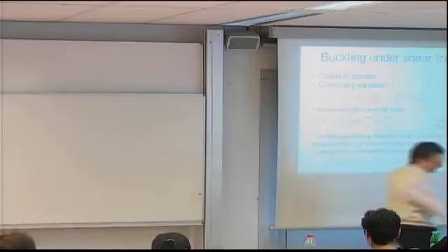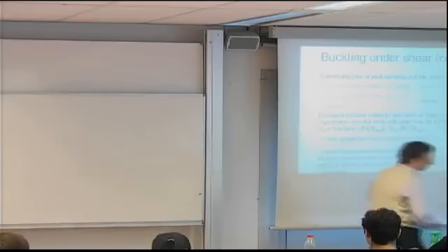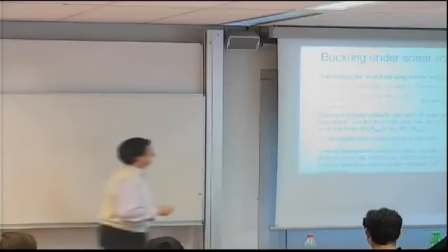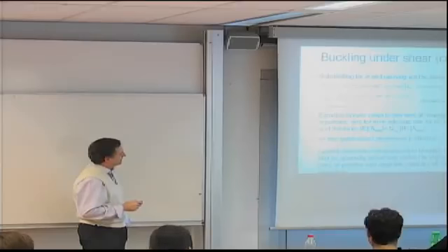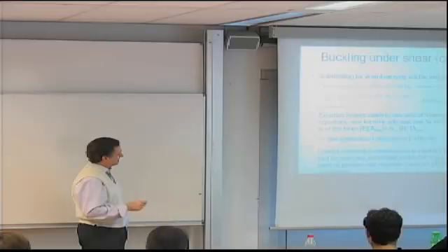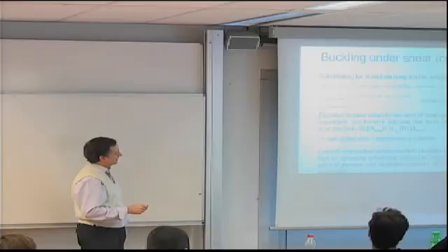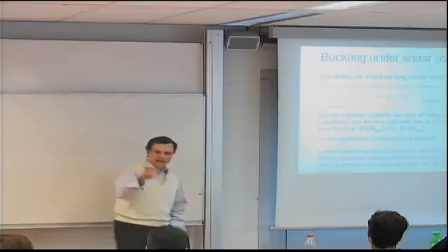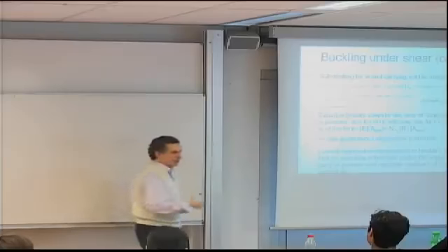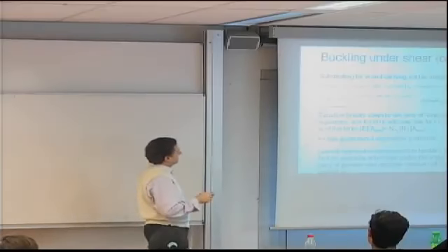Still, the algebra is not straightforward. You substitute in that equation at the bottom from the previous chart, and you carry out all the integrations, and you find this equation shown at the top here, which involves these D matrix terms, and then some terms that involve the applied load NXY with a bunch of matrices. Tij, Aij here are matrices. The Aij are not the A matrix, it's the AMN coefficients that we're looking for, so it's a vector, and the Tij are given by this quantity. It's just a function of the indices.